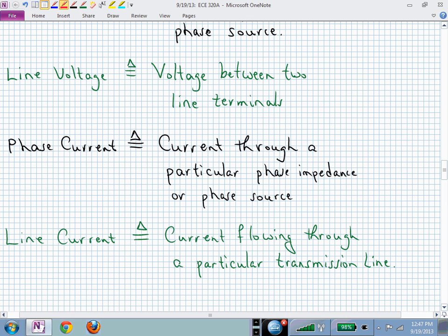Now just draw your diagram and say, okay, when is the line current going to be the same as the current going through an individual impedance? Pardon? Why? Is that a question? WHY or WYE? It's the Y configuration, isn't it? The WYE. The line current and the phase current are the same in the Y configuration. That has different interpretations, just like 2, right? TO, TWO, or TOO. And we will use them all today.